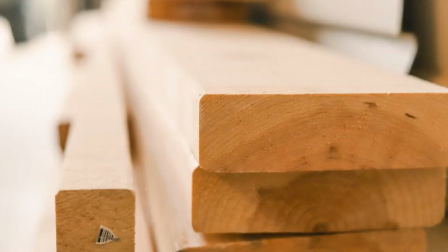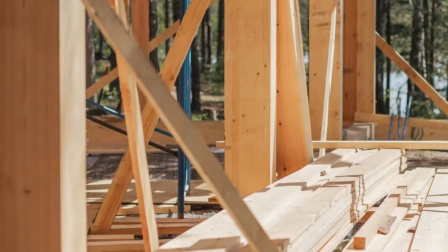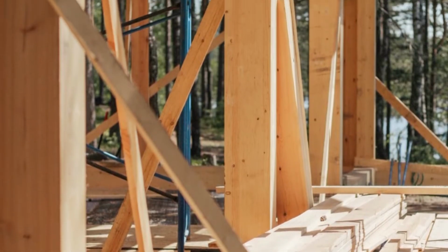Number 3, advanced structural framing, using less structural materials by lining them up from floor to floor and from roof to floor. Number 4, consult with your HVAC, your heating, ventilation, and air conditioning sub-trade or an engineer, and ask him how that can be incorporated into the water heating system. So instead of having single-use equipment, heating and cooling for your air and other equipment for your water, you can actually combine this, and that will bring down the amount of equipment that you need.